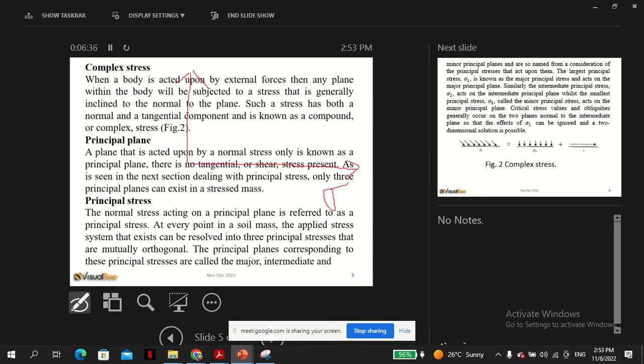So we plot stress here and the shear stress. Normally we plot sigma 3 here and sigma 1 and draw a nice circle here. You can see here the shear stress is zero because it's just on the horizontal axis, the same here. But anywhere else, there is a sigma value and also a tau value.